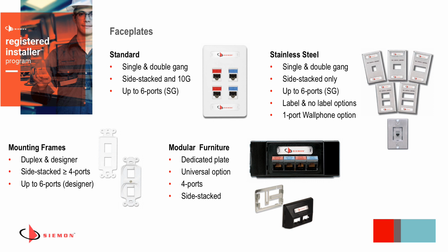But some customers just prefer the look of having distinct outlets with a little bit of space between them, so they can certainly be used for anything that's not necessarily a 10G application. You can fit up to 6 ports in a single gang faceplate if they're all stacked side by side, or up to 4 if they're stacked discretely, and that goes up to 12 ports when you're talking about a double gang type of version. We also have a stainless steel option, which is shown on the right.